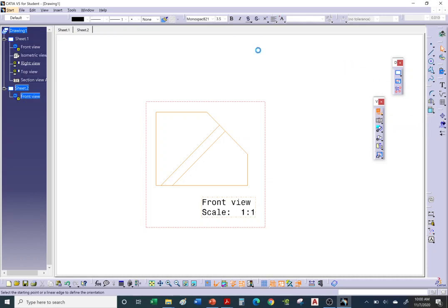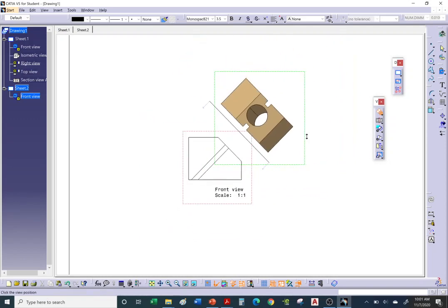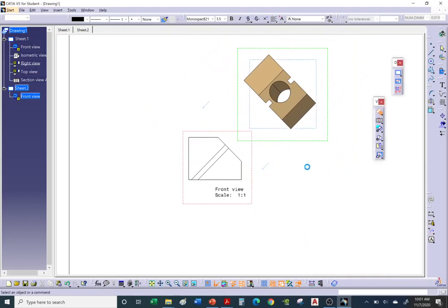Auxiliary view. Okay, so just guesstimate where you want your line of rotation. I'm going to click. Then I want to be parallel to this one. So I'm going to track it, see if it tracks, and there it is. It tracks. See how it's giving me parallelism? I can always right click and say, hey, I want to go parallel to that line. And when you're ready to generate your auxiliary view, double click, and it'll generate that auxiliary view.